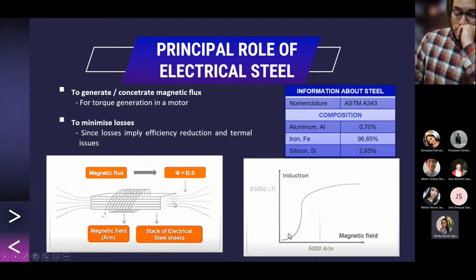The goal of laying electric steel is that when you put steel inside of the copper coil, more current will be generated than if nothing was put into it, and that is due to the fact that silicon steel is ferromagnetic. Such behavior is required in the magnetization graph that provides the amount of magnetizing current that is needed to achieve a certain level of induction.